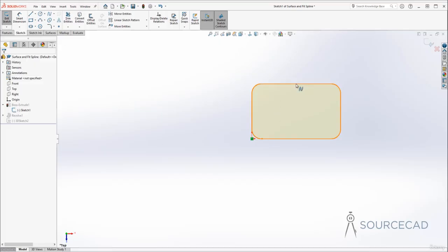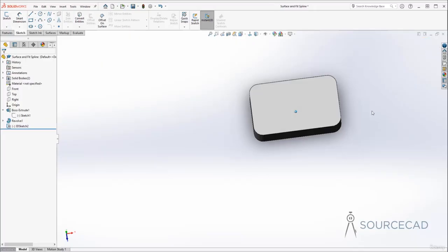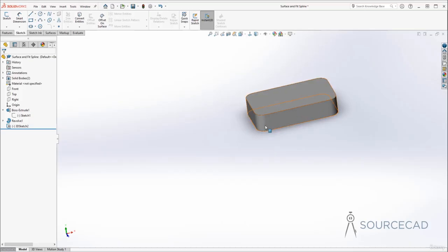And here we are. We have got a completely clean spline. Now, of course, this is a simple spline, so we don't have any kind of fillet anymore, but this will resemble the main geometry within a tolerance value of 0.01. Now, if we exit this sketch, we will end up with this. And as you can see, we no longer have all of those creases here. So we have a completely smooth surface here. And if you just go on and machine this thing, there won't be any kind of crease right here. So that's another way you can use Fit Spline tool to get smooth surfaces wherever there are sharp edges or all of these creases.